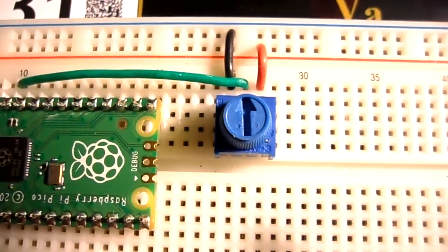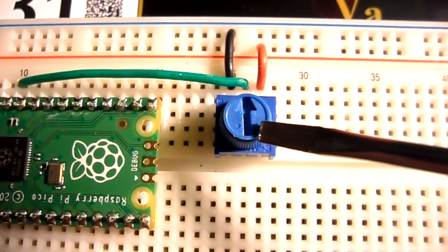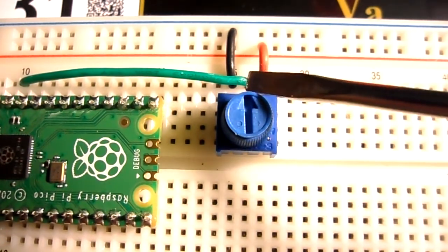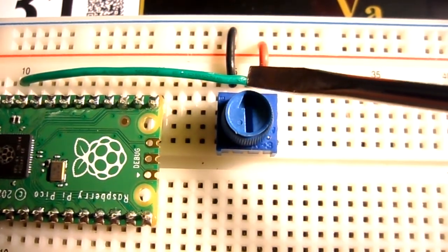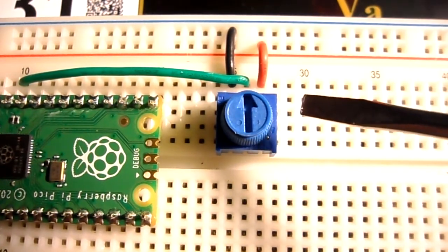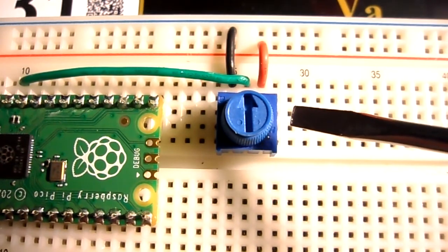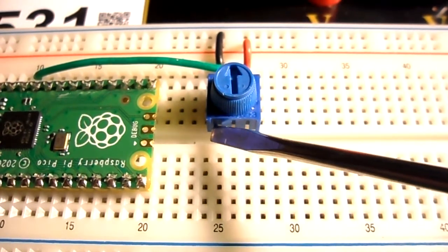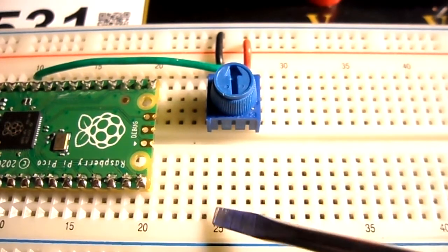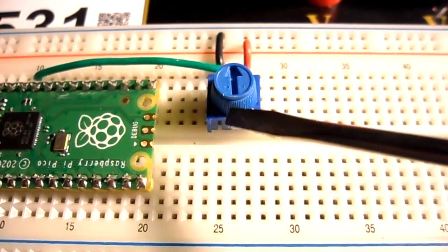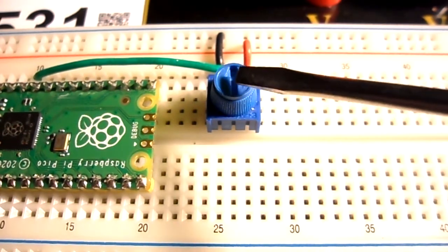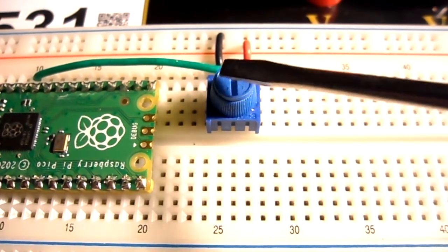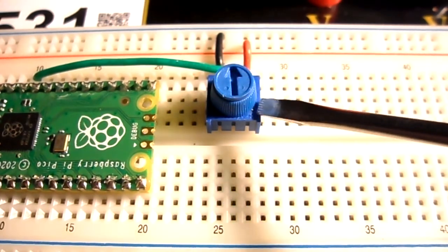So I'm going to start off my readings with the potentiometer, and it's going to be in the centered position. So you can see the little arrow on here is in the centered position. So it should read somewhere between 0 and 65,000. So halfway should be somewhere around 33,000. Please note the orientation of my potentiometer. The bottom edge is towards the bottom of my board. And in this position, when I turn the knob on my potentiometer fully counterclockwise, I should get my lowest reading, and when I rotate it fully clockwise, I should get my highest reading.